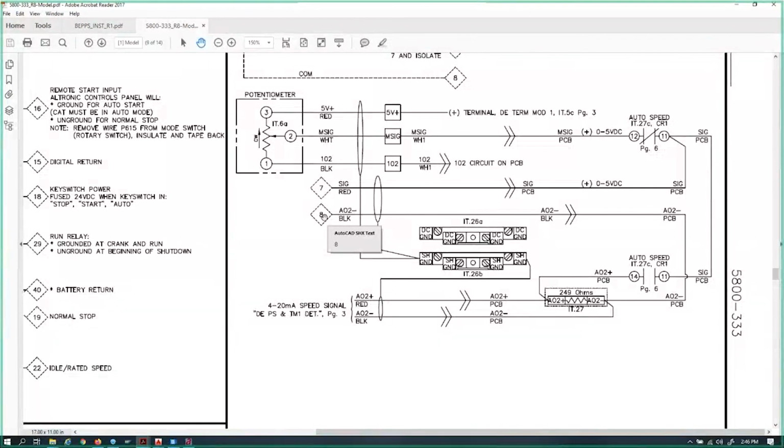And for those of you who took the first part of this class, do you remember the formula? We used the term 200 ohm that day, but in this case it's 250; you can round it. So if we write out 4 milliamps, 0.004 times 250, we're going to come up with 1 volt.